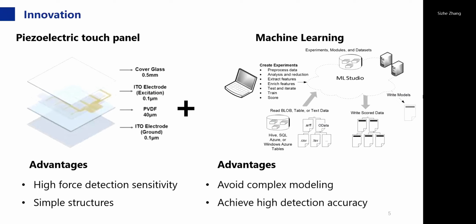The choice of employing the piezoelectric touch panel is due to its high force detection sensitivity compared to piezoresistive and capacitive-based architecture. However, products using piezoelectric materials have faulty detection accuracy because of the unstable force-voltage responsivity and unavoidable interference. And what it specifically refers to is the propagated stress resulting from adjacent force touch. The issues above will become more complicated when two force touch events occur simultaneously. To sum up, it is difficult to establish a physical model and apply formulas to solve the problems.